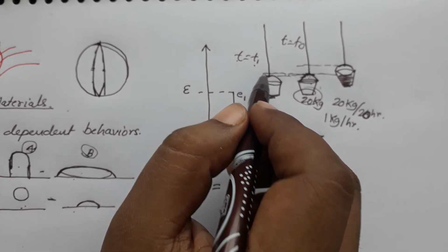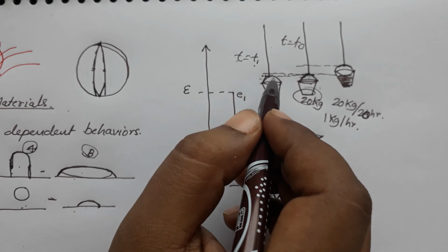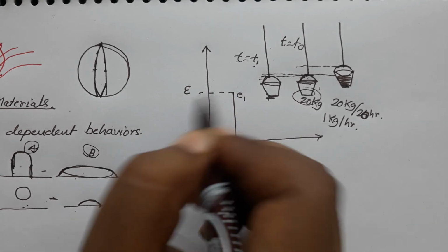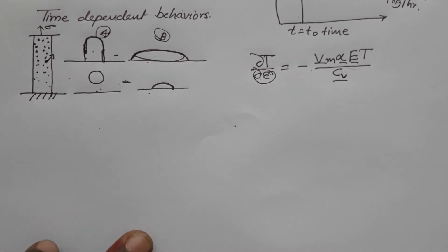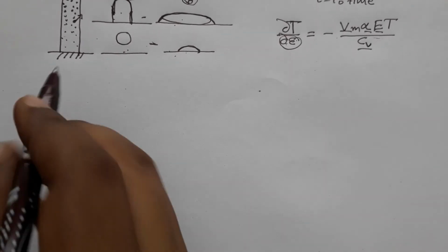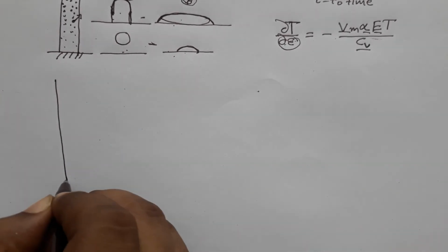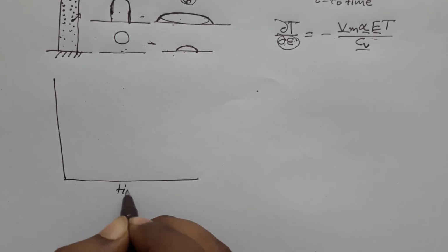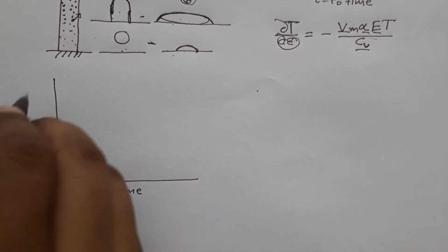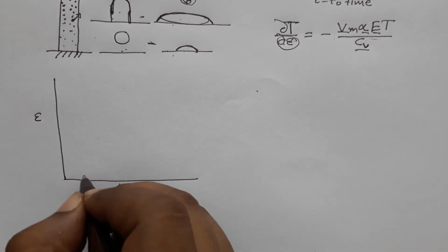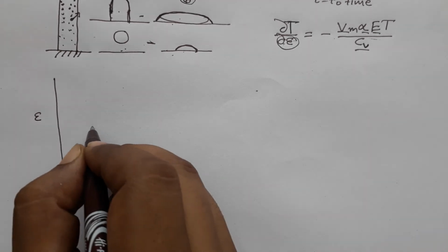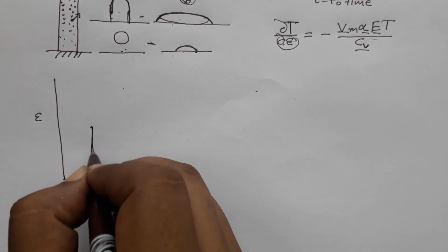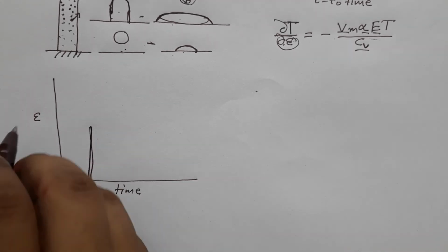Okay. So, this phenomenon is called elastic after effect, and this change in strain because of time is called inelastic strain. I should describe it to completion. So, let us say at t equal to 0, you apply a certain amount of strain instantly.